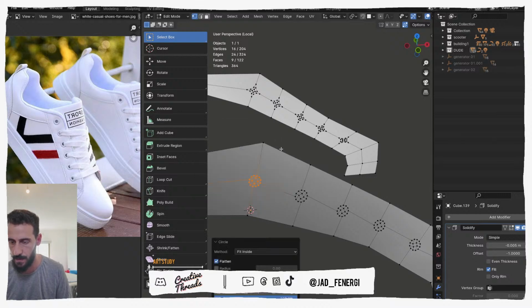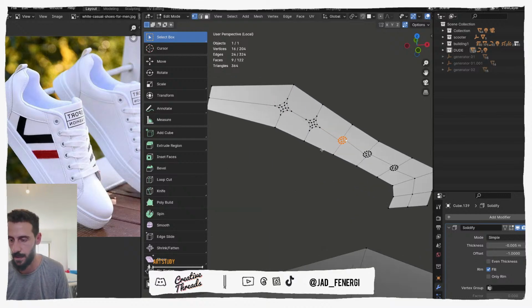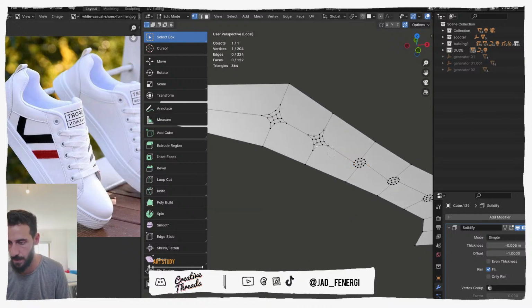Loop tools, circle. Shift R, press C. Pick them. Sorry. Press C, select these. Shift R. C, select. Shift R. So the Shift R here is just repeating the last command. And the same thing in here.